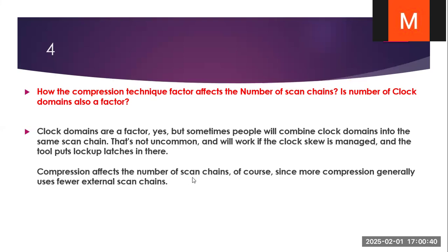Does compression affect the number of scan chains? Of course, yes. More compression generally uses fewer external scan chains. Normally, these external scan chains are called scan channels. The internal scan chains, we call them scan chains.